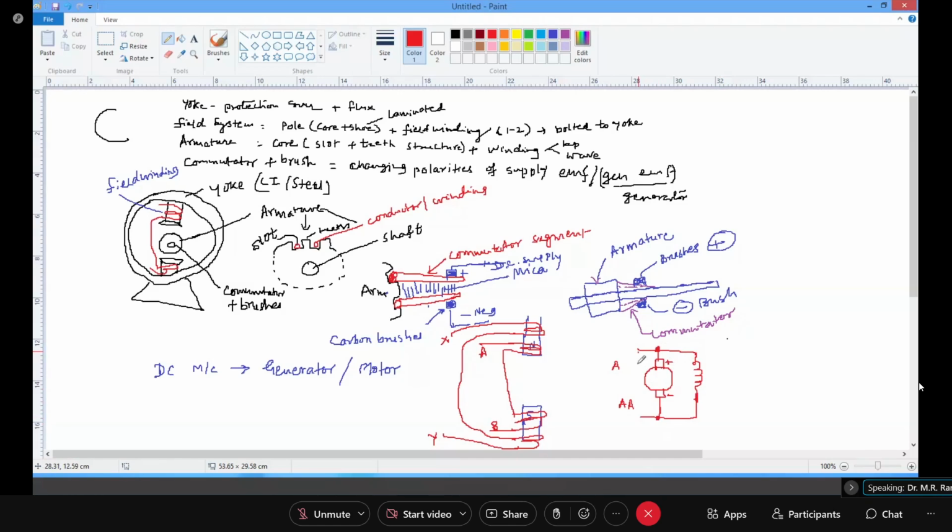Here there is a DC supply. So when I connect the field winding, I name this FF. It may be F1, F2 in some laboratories. When I connect the field winding parallel to the armature, or you call it a shunt, then this A is this one.